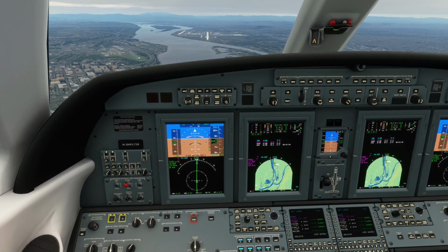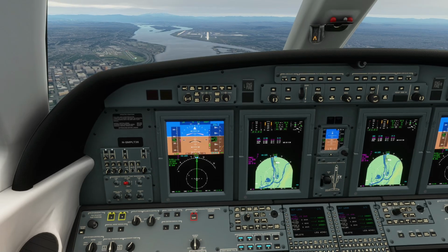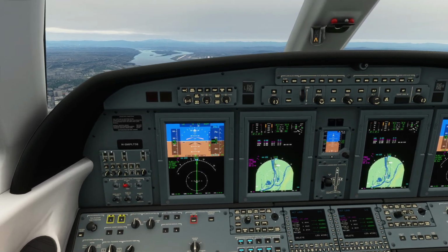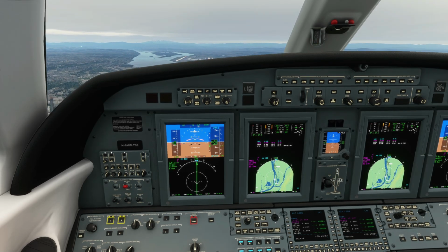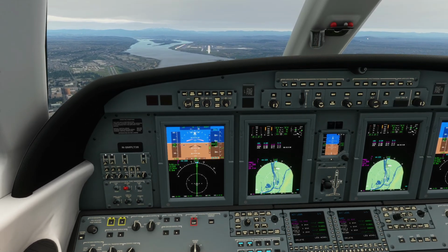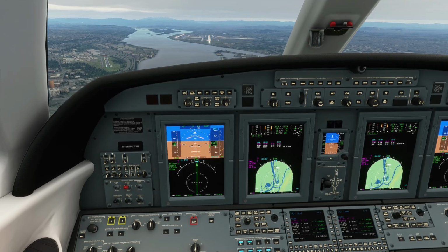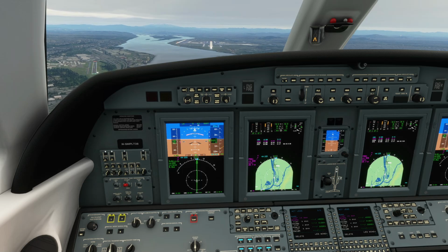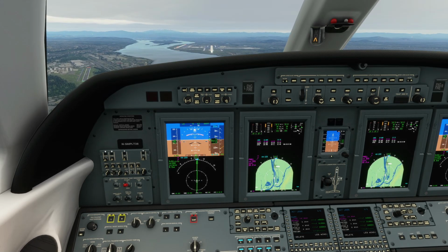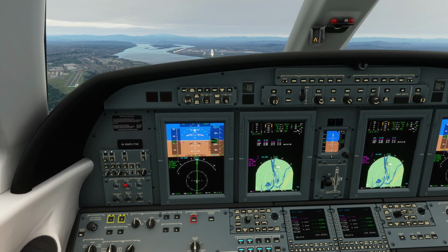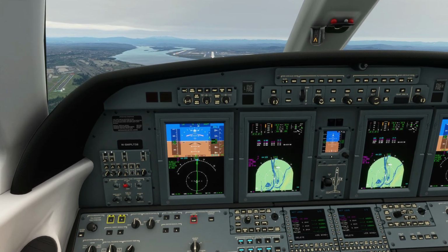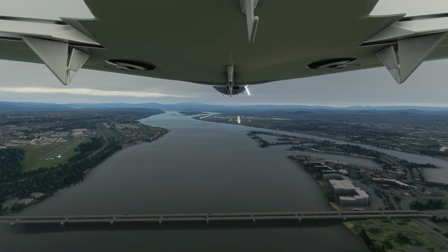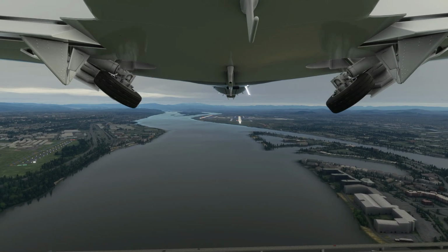Yep. Drop one level of flaps. Pitch again and trim the aircraft for descent. Not that much, that is too much, just a tiny bit. Yeah, there we go. Follow this, correct ourselves, the flaps are out, so we are coming low. Let's see here, landing gear is coming down.